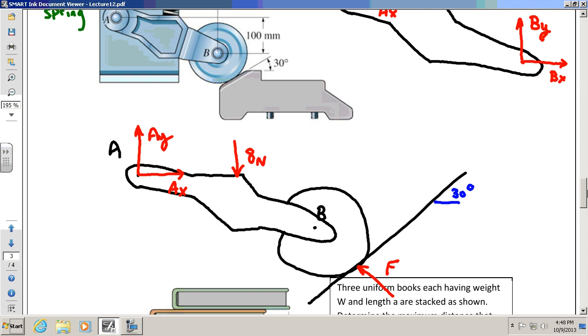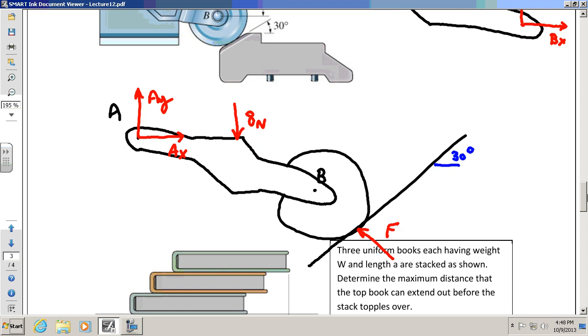This way, point B became internal, and now I only have 1 unknown force there at the end. Because it's just a rolling contact. It's a roller, and if you look at a roller, previous lecture, roller means force that's perpendicular to the surface, like that. Okay? That's great, because now I can solve it. So how do I solve it? Okay, well, what you want to do is write a moment equation again. Those are always nice. Okay? Write a moment equation. Okay?